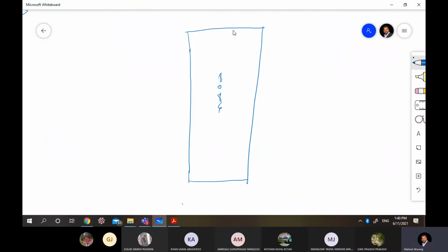Once again my aim is what, to just make those three things separate: address, data lines and control lines. ठीक है, कैसे करेंगे देखो. Now for each IC we require this particular thing, that is a clock. So what I will do is that I will just use a clock generator over here. So here I will have that 8284, to which I will connect a crystal oscillator of some desired frequency, and here we will be getting clock, reset and ready.